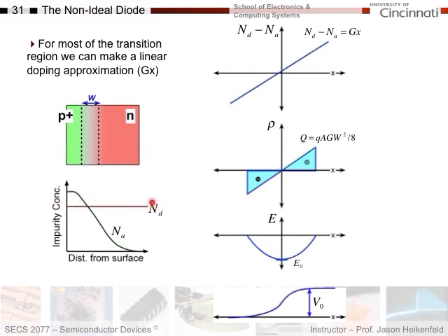The boron you're diffusing in, and you get a higher concentration right here at the interface. And as you go deeper in, it doesn't diffuse in as far, and it drops off versus distance. And so what you see is your junction will be where the P-type doping drops below the N-type doping, and you start to switch over to N-type. This side's P-type, this side's N-type. Which dopant dominates?